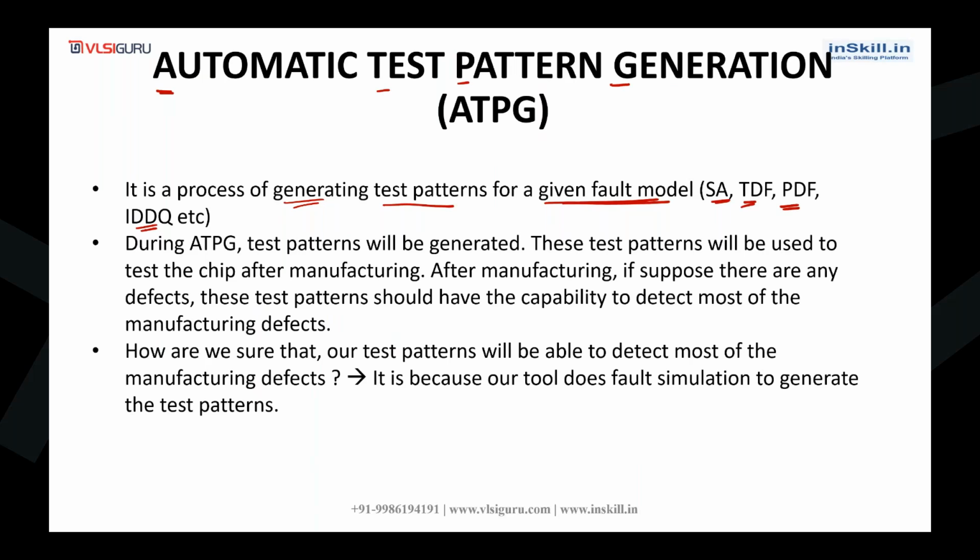During ATPG, test patterns will be generated. These test patterns will be used to test the chip after manufacturing. If there are any defects after manufacturing, these test patterns should have the capability to detect most of the manufacturing defects.